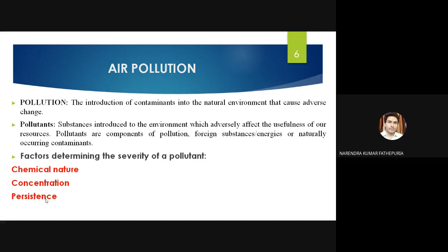There are various air pollution measurement devices: air samplers, analyzers, volume samplers, and NOx samplers, also for capturing the particulate matter concentration. We have particulate matter PM10 and PM2.5, right? So we have various pollutant measurement devices. We have to check the concentration in the air first. Then we can tell the severity of the condition for the particular type of pollutant. Of course, these pollutants have a bad impact on human beings everywhere, right? That is what we discuss when talking about the impact of air pollutants in the atmosphere.